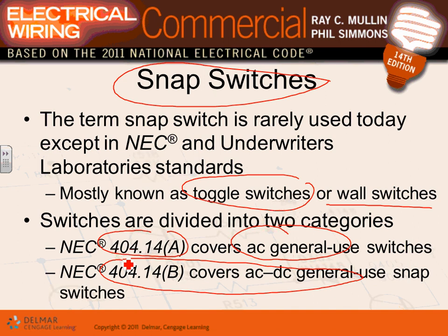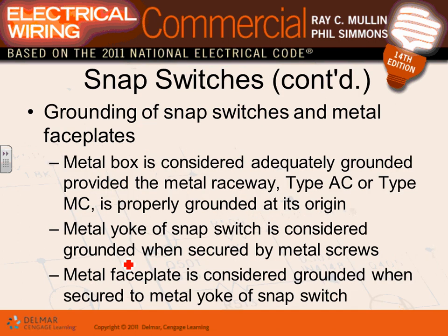Most of the switches that we design are rated for AC, because we distribute power with AC. Now the solar photovoltaic system is coming a lot. There might be loads that are fitted at the DC level. So when you have a switch on a DC circuit, make sure that your switch is rated for DC if you are to install it in a DC circuit.